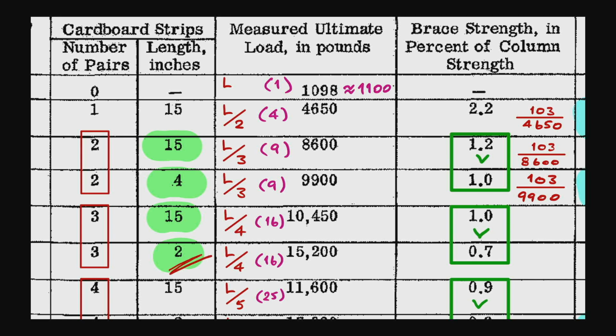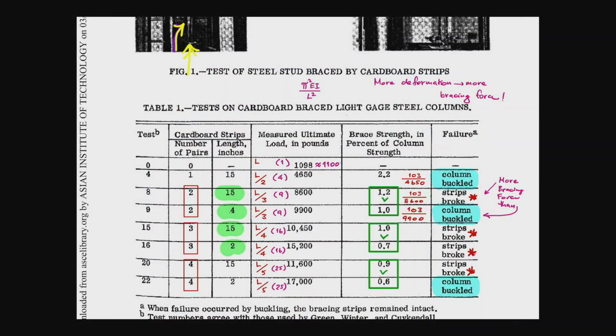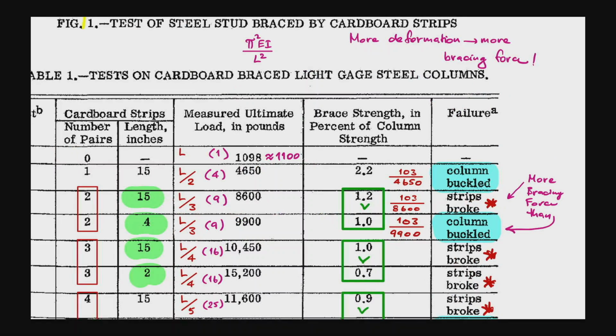And you can see over here the recorded failure mode, and this is important when you run the physical specimen testing. The failure mode should be very well recorded, and then the analysis of the failure mode is going to give us a lot of information. So if you by chance run physical specimen testing, if it is RC, then you're going to record the cracks: how it starts, where it starts, how big it is, what kind.